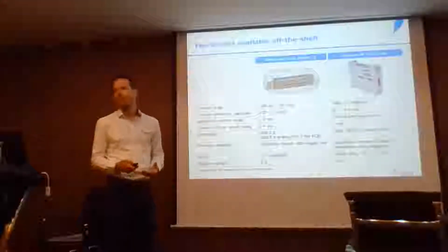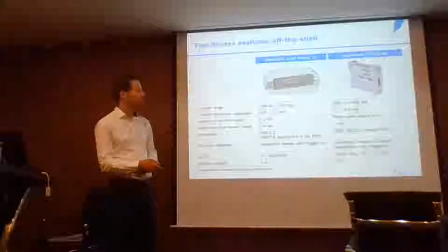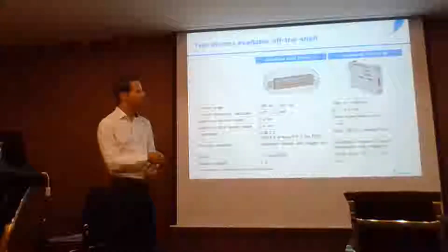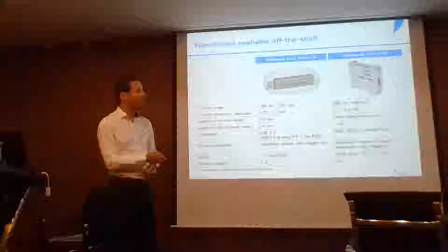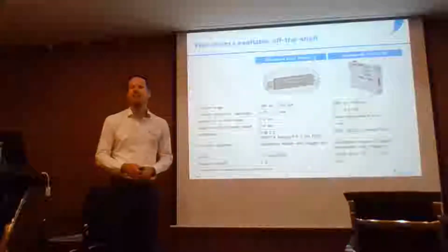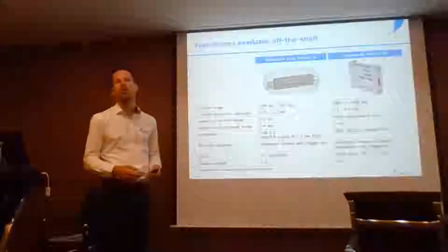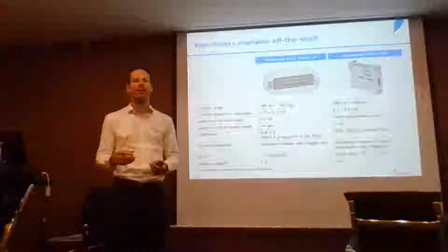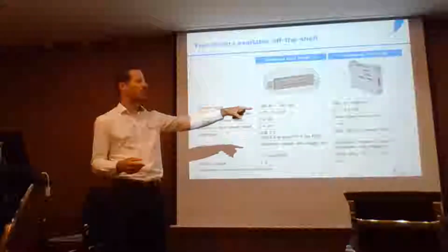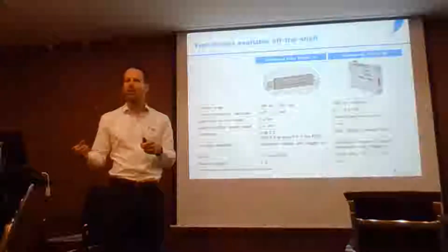But for industrial purposes, sometimes USB is not so good. So many customers like to work with gigabit Ethernet or use the analog interface. And actually, the analog interface, 0 to 10 volts, is very well programmed for the Gardasoft controller. So you can use it to have this kind of closed loop control where the lens follows the analog voltage.